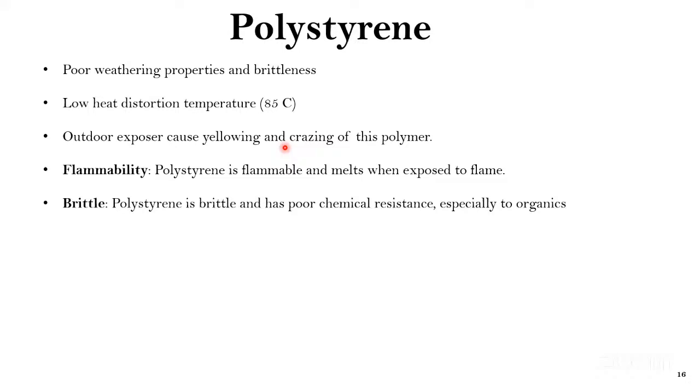Once you see a little bit of yellowing occurring, you have to know that the polystyrene is going to degrade soon, and then it will start to separate or break into very small pieces. So for outdoor applications, it is difficult for polystyrene alone.